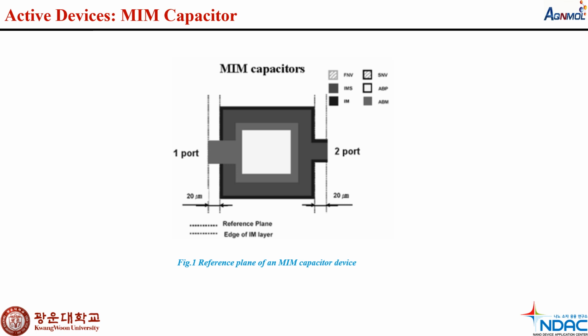It means metal insulator metal capacitor, which is shown in figure number 1, because of the high capacitance per unit area that can be obtained. Therefore, smaller and less costly circuits are possible. The thin film capacitor is composed of two metal plates separated by a dielectric material layer. Typically, the dielectric material layer overlaps the first metal layer, and the second metal has a smaller area than the lower metal area. The area of the air bridge post determines the capacitance value.